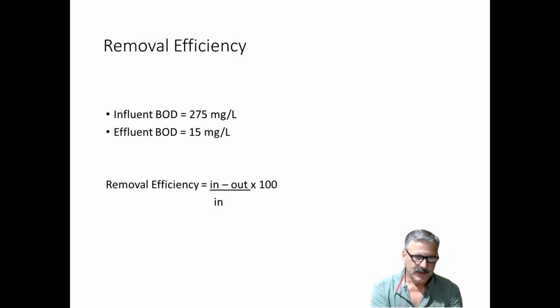Removal efficiency is the same calculation for any of the tankage and, like I said, any of the units that they might be looking for. And the calculation is in minus out divided by in times 100.